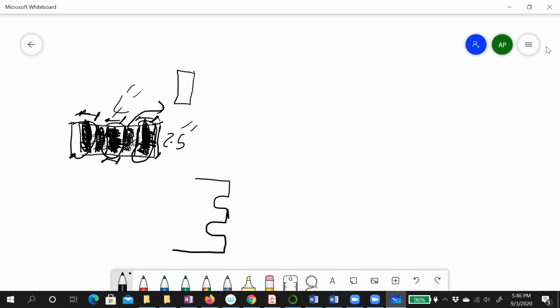So assume we have this tension force. Then it makes a stress just here. So this is nothing here. So then we take this length minus these two pieces, times the thickness. This is the area that contributes to the stress. Those things you see with pi, we don't care about them.